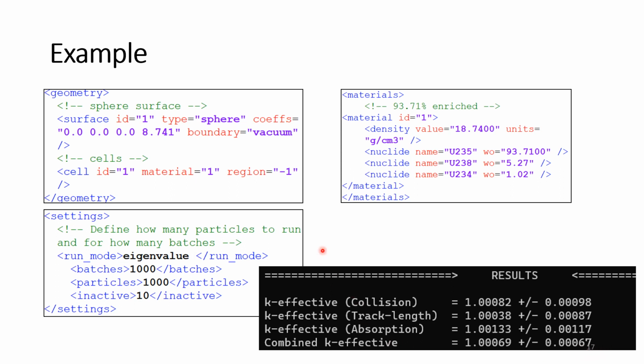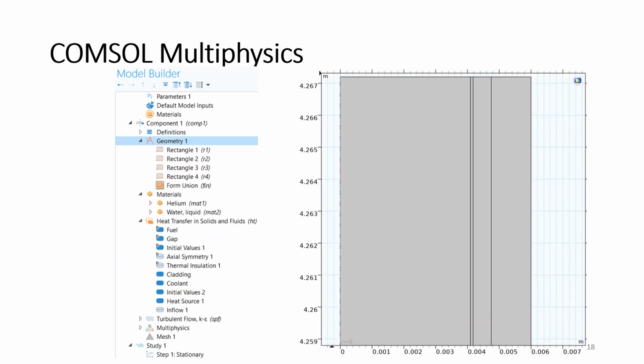Now, a typical stochastic simulation would give you a mean plus a confidence level as a relative standard error to tell you whether your result is accurate and precise. Now, it could be precise and not accurate, so you want an estimate which is both accurate and precise.